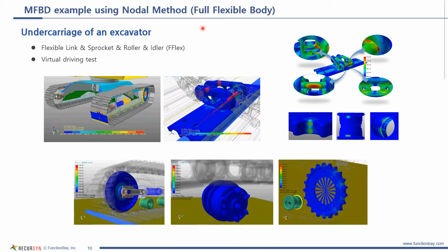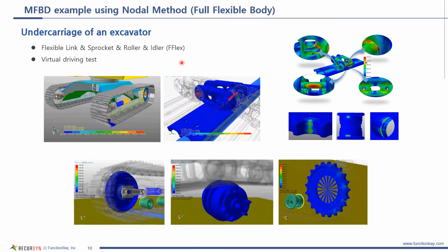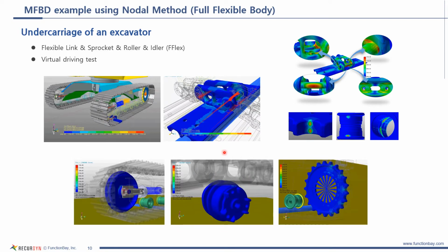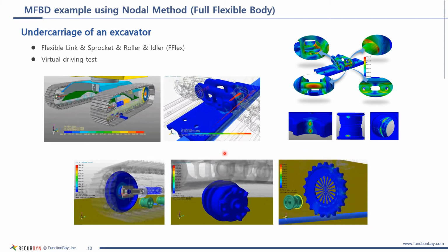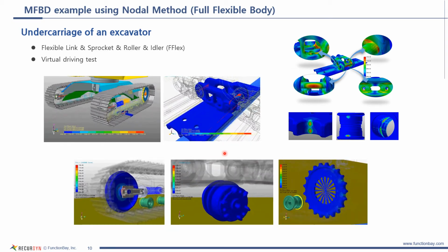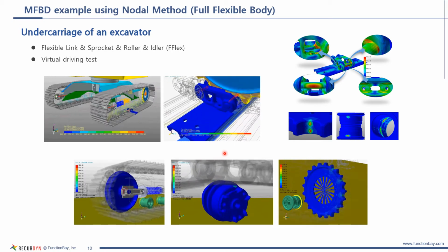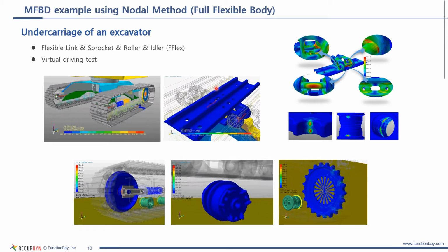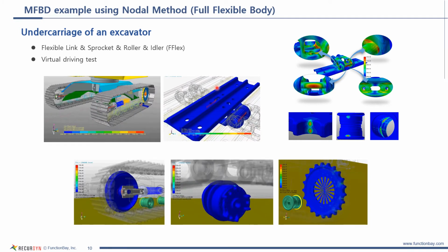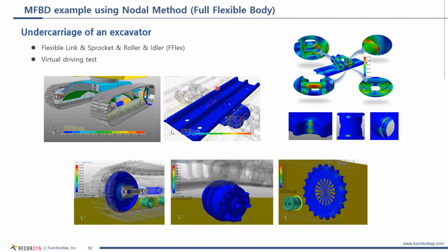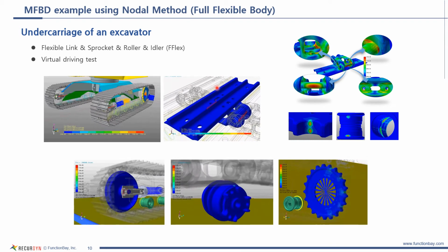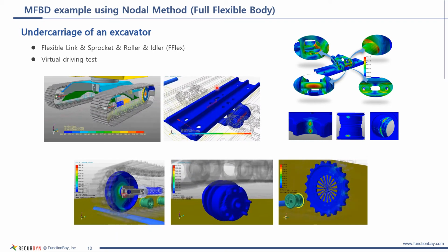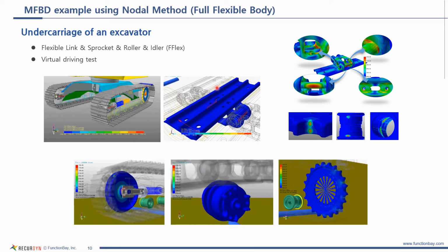For the undercarriage of an excavator, some parts such as links, sprockets, rollers, and idlers are generated as flexible bodies, and the virtual driving simulation was performed. It is possible to analyze the stress generated in links, sprockets, rollers, and idlers while driving and even evaluate durability.